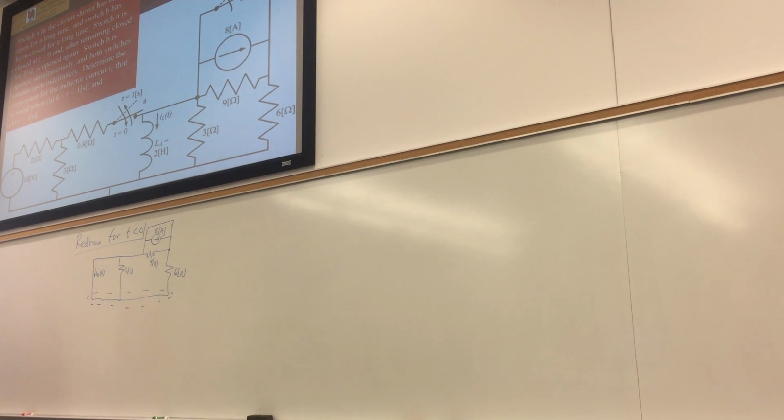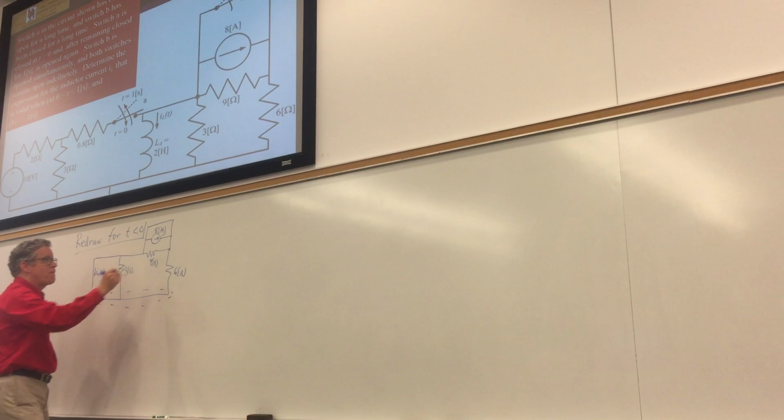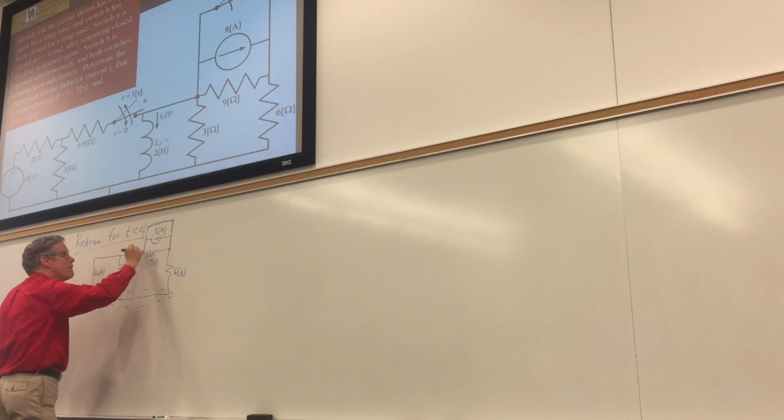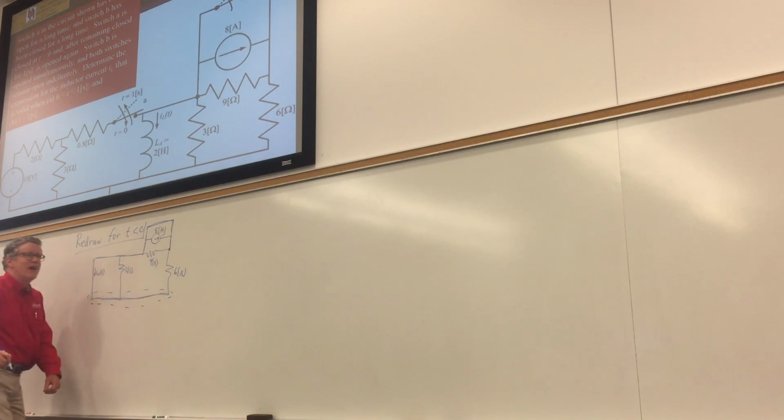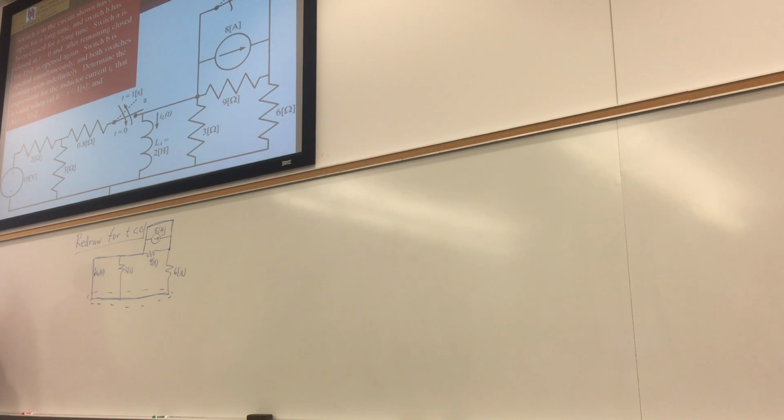What's the point about the 6 ohm resistor? Oh. Surrounded by a wire. It's got 0 volts across it. It's a big long wire. We don't care. There's a wire across it. Which means you got 0, which is the answer he got even faster.